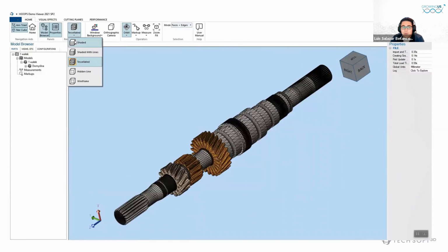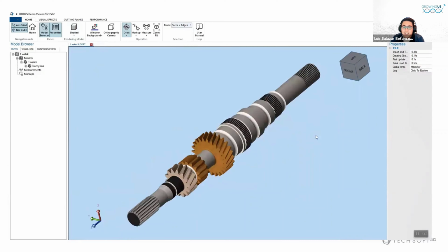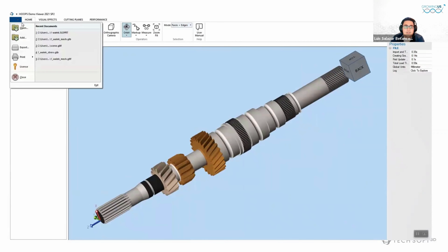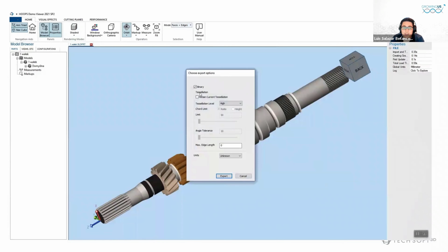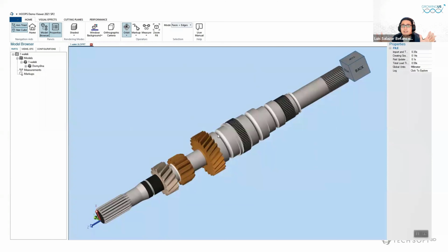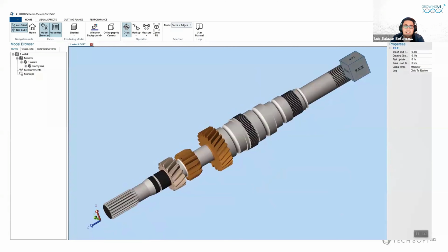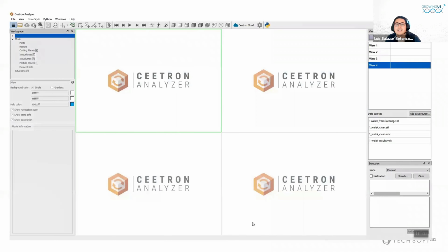So when opening the CAD model, we see a first tessellation that will be the key ingredient for the following demo. We will export this first CAD model into a file that we'll call the wheel front exchange. So I am exporting it in binary with a high resolution for the tessellation, and then I have created an STL file. Thanks to Hoops Exchange for generating that. Then I will move to the world of CAE.